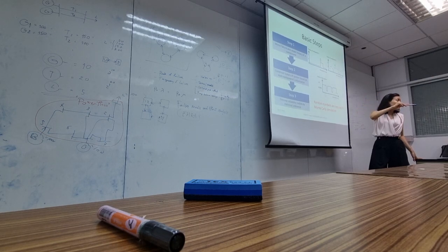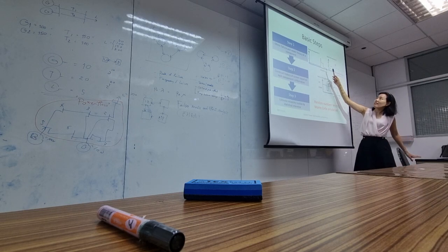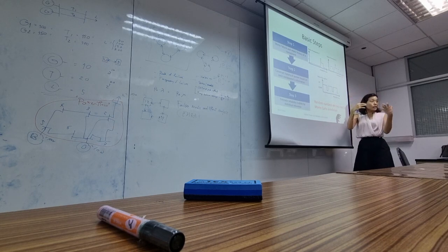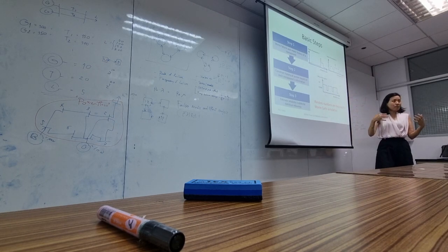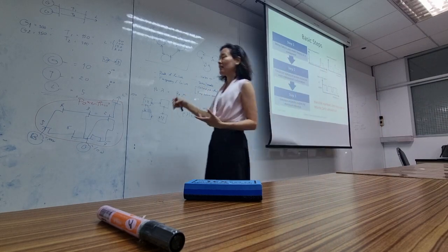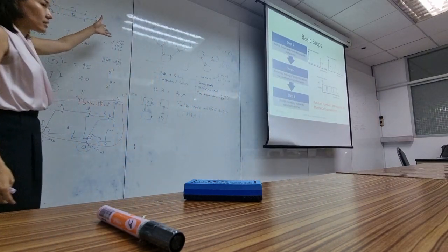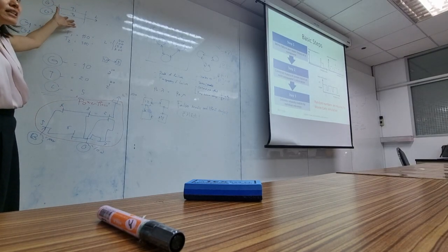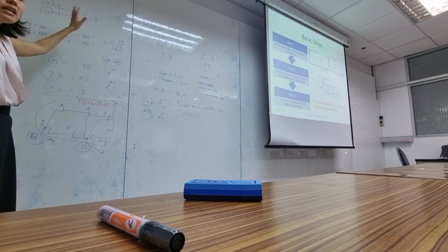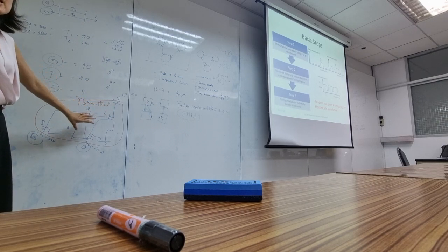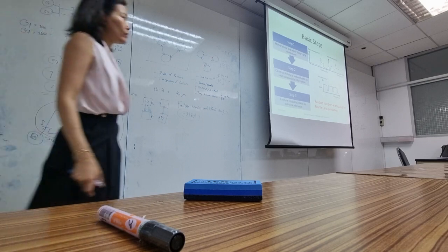Find out first what states each component is in, and then use the states to go through the topology. What it means by topology is that you need to find out how it's connected, whether it causes system failure, right? If it's simply connected in series or parallel, it's easy. If it has a lot of connections, you need to use power flow. Okay.